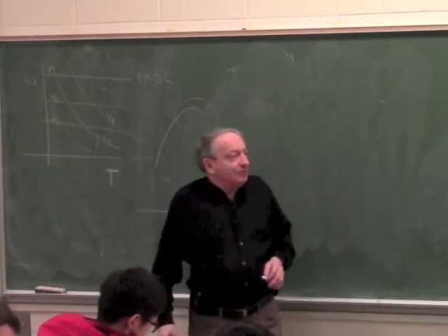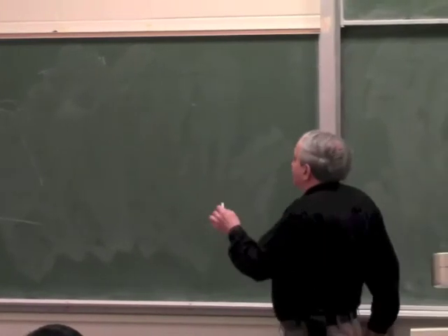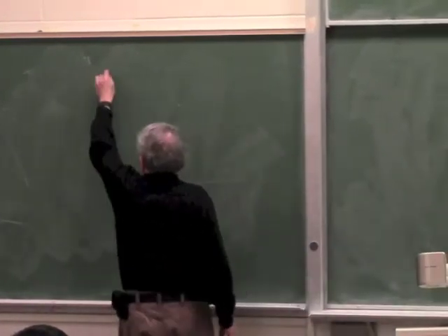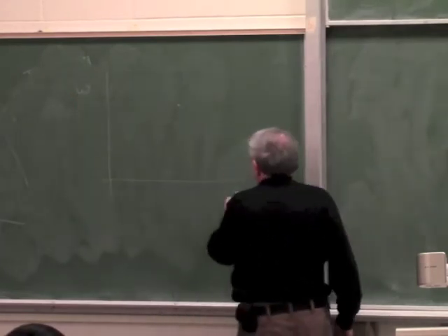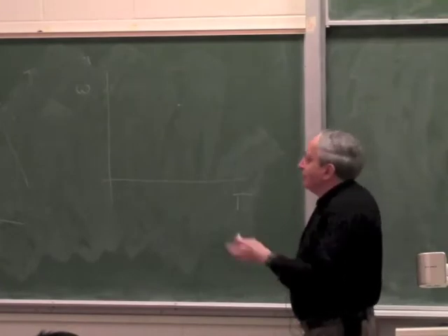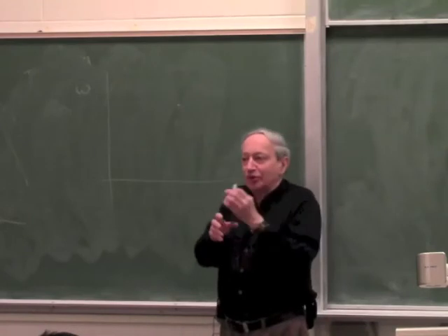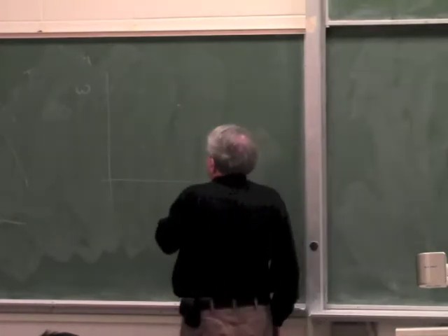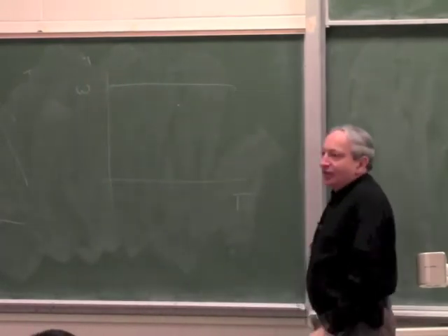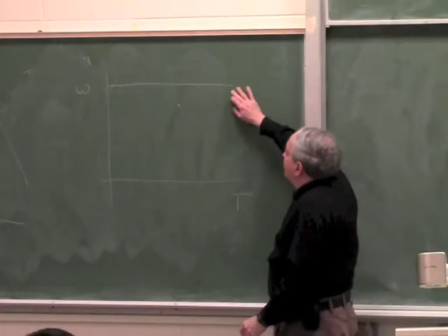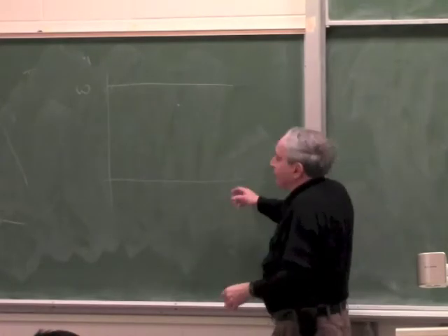Okay? Now when we talk about rotating field motors, things are a little bit more complicated, because let's start with a synchronous motor. If we draw omega versus torque for a rotating field motor, since it's a rotating field where the magnet of the armature is locked to the rotating field vector, when you change the torque, the speed doesn't change. Okay? Now, simplistically, you tend to draw it like this, that at a certain torque it breaks lock.